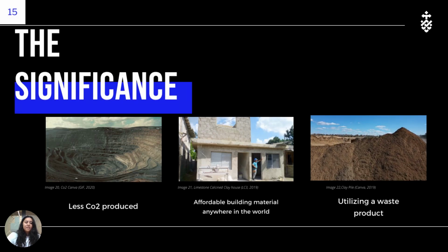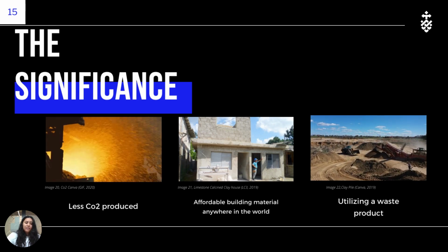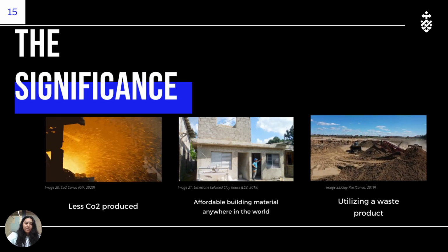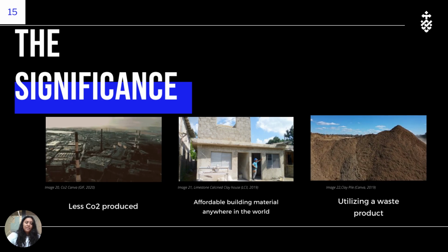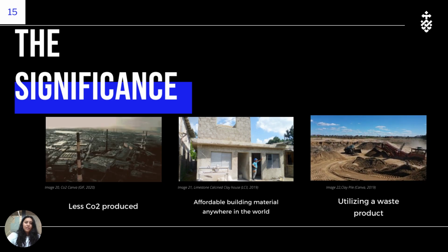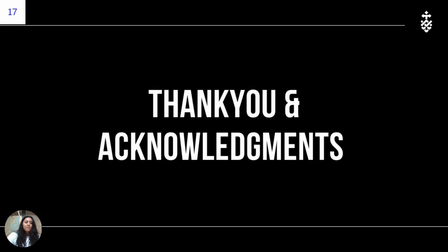The significance that LC3 brings is fundamental to the growth of the concrete industry and is a solution to more sustainable concrete. By utilising LC3, not only is less CO2 produced, it gives access to produce affordable and a sustainable product without sacrificing the strength of concrete, whilst also utilising a waste product. This research is a starting point improving LC3 viability here in Australia. However, continuous research is needed to continue the building case study.